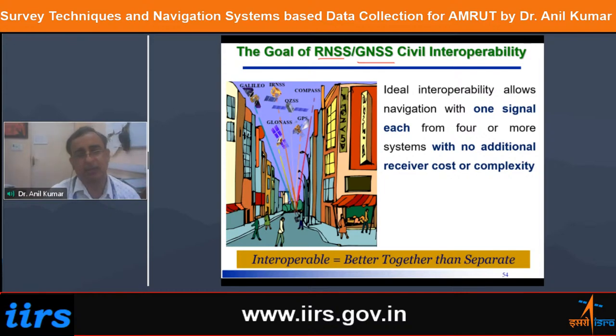Second thing, the geometry of the satellite. Whenever we are doing measurements over 24 hours, the geometry of the satellite is very good. When the geometry is very good, the error in the observation comes down. We can understand the geometry like this: if there are 4 satellites clubbed very near to each other and I'm doing observations, their geometry is poor. They are not well distributed.